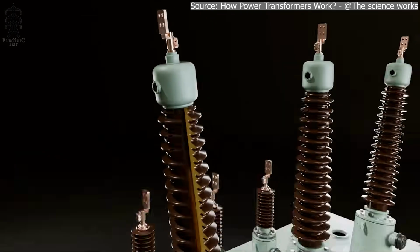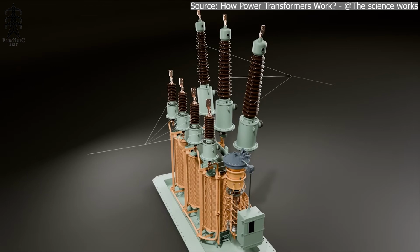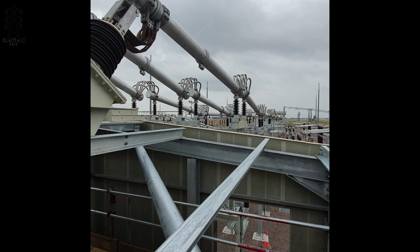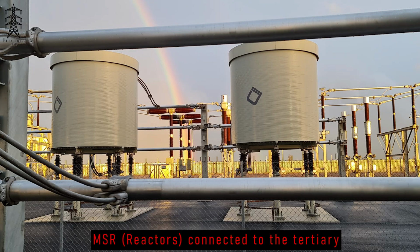The high voltage side of a transformer usually has a higher and thinner bushing, whereas the LV side usually has a smaller and wider one for the higher currents and lower voltage. Depending on the transformer, you might find an additional set of smaller bushings on one side, known as the tertiary bushings. This connects to the tertiary winding and can be used to power an auxiliary transformer, connected to earth as a neutral point, or used for voltage regulation.